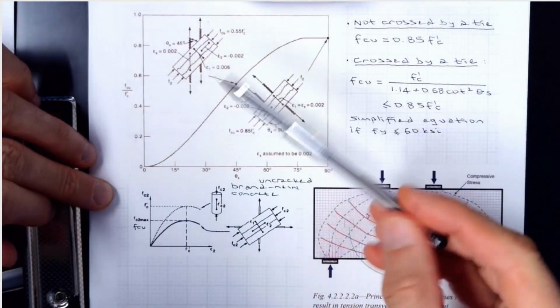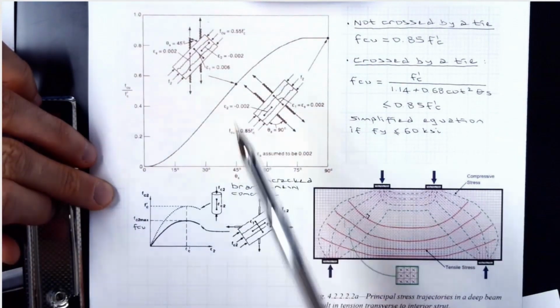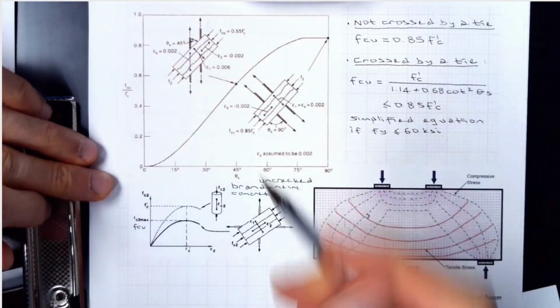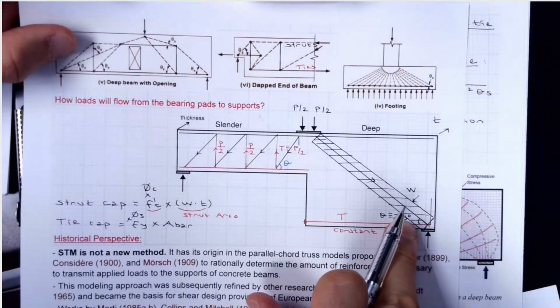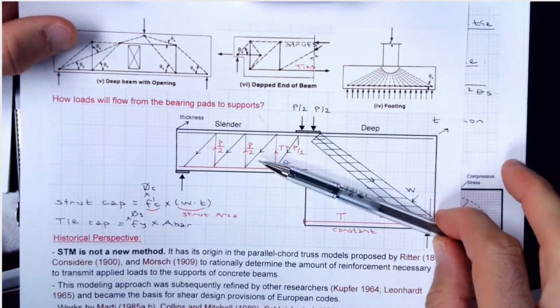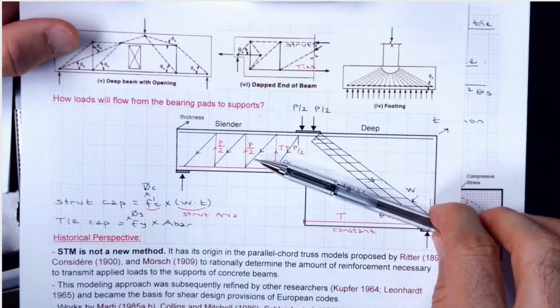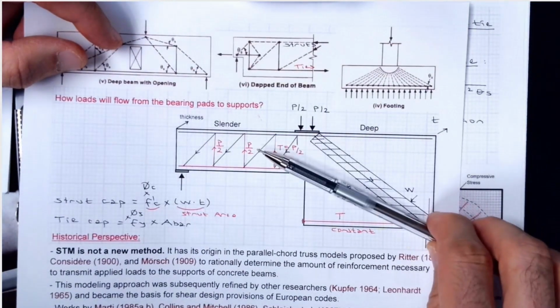So you can see how theta affects f'c. This is what I meant in the previous example. The shallower the theta, the worse the condition would be. Theta is everything for a certain strut-and-tie model. Shallow angles indicate inefficient models. They indicate slender behavior. It's associated with slender members.